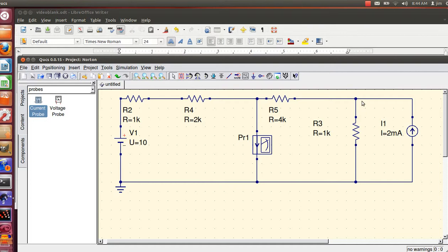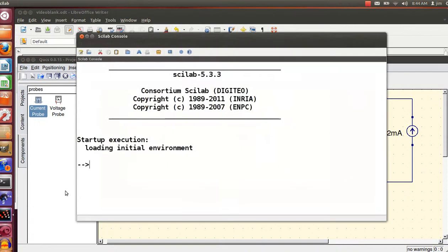And then for my fourth equation, the current coming into here, the voltage drop across this, and the voltage drop across that have to be the same, because essentially they're in parallel, because if we look at this as being nothing. So these two voltage drops have to in fact be equal to get down to equal potential on this side. That gives me four equations, and I put them in standard matrix form so I can solve them.